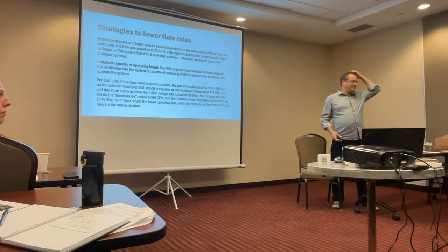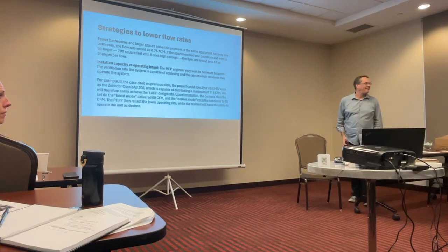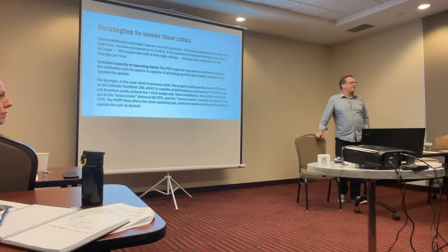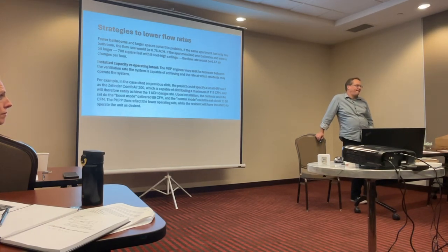You still have the same flow rate with that larger volume. The flow rate's what's dictating your energy loss. So even if you had a bigger volume, and the reason I know this embedded in my head is because I messed it up on Cornell. I was assuming during my drawing, my design and my PHPP stuff, that I was going to have 0.5 air changes per hour, and we put in the flow rate 20 because the volumes are enormous. And 20,000 square feet is very different than 10,000 square feet. So it's the flow rates that actually dictate.